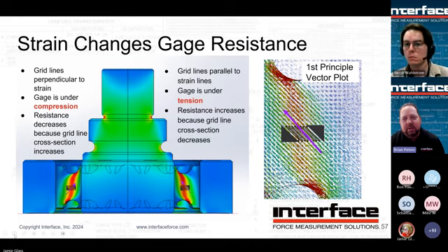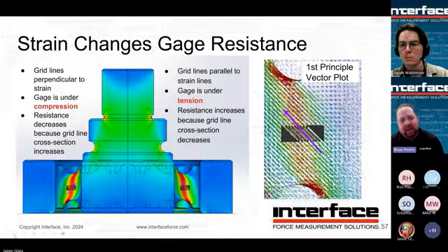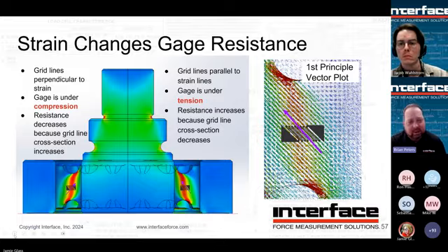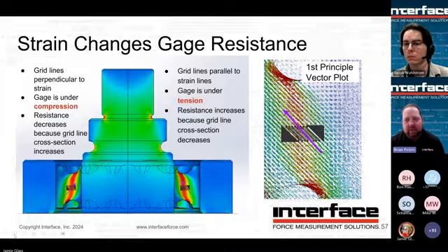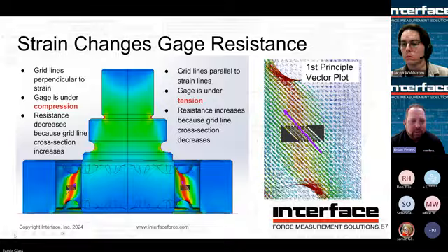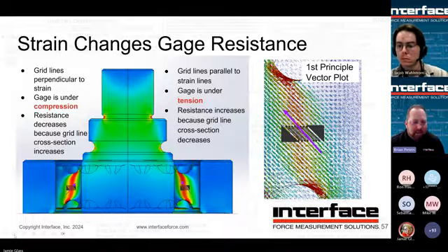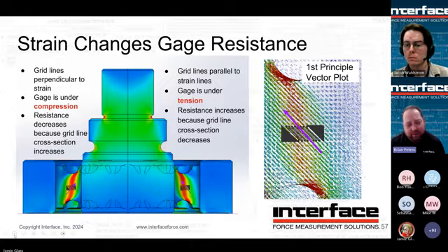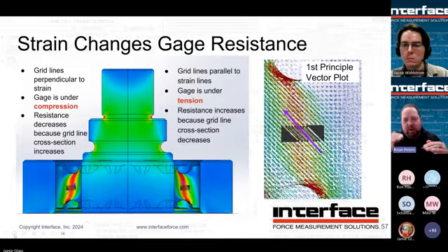to the bridge. So if you look at our calibration grade sensors, for example, our 1600s, they have a pre-installed cal adapter. So that center stud that we see here in this picture would be threaded in, it would be locked at the factory, and it would be preloaded to ensure that as you operate within the capacity, you're not going to get any change in how those threads interact with the center hub to ensure that you don't get sudden shifting of which threads are loaded, where the load goes through, which can then dictate a very slight, subtle change to the beams, right?